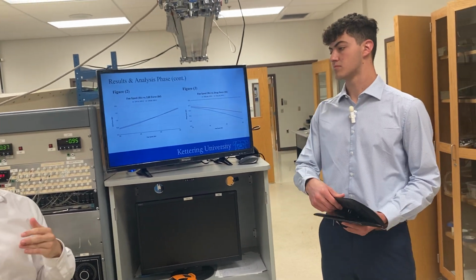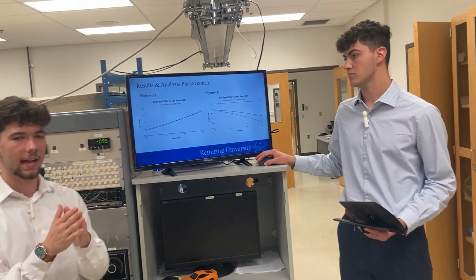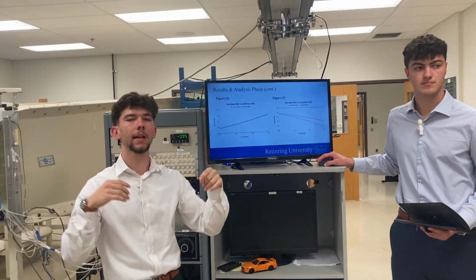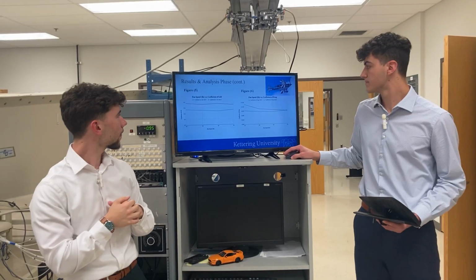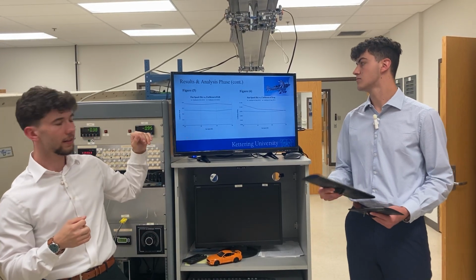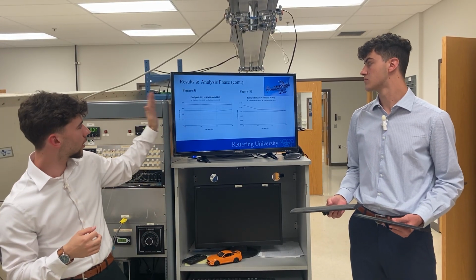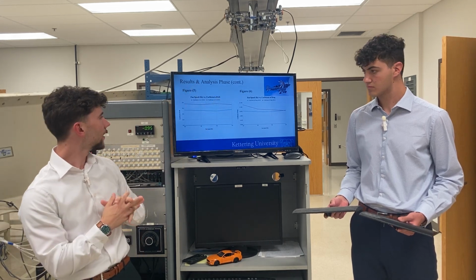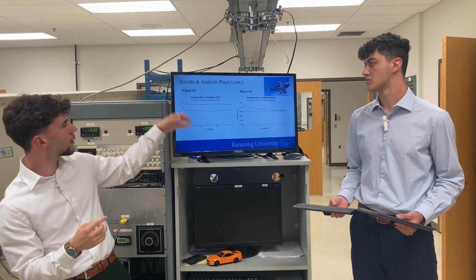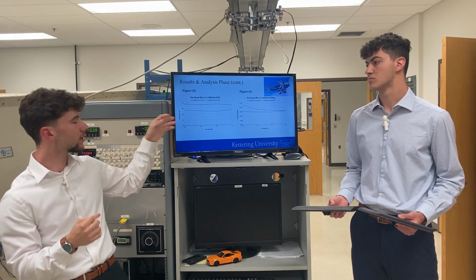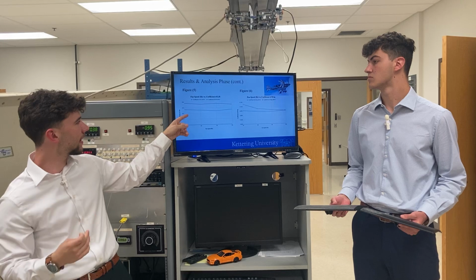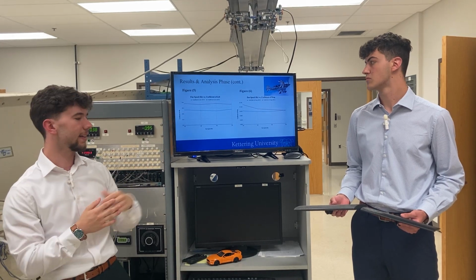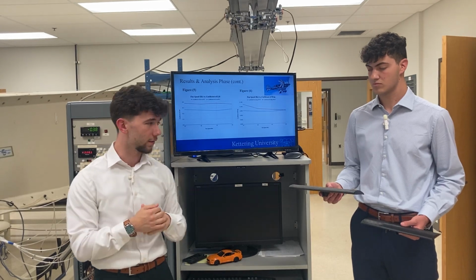This is what we would expect from a foil with a high aspect ratio, as you get longer and skinnier, the wingtips are going to be farther from the base of the wing, meaning they are going to produce less drag force. Figures 5 and 6 here are the fan speed for each foil versus the coefficient of lift, and the fan speed for each foil versus the coefficient of drag. Now here, again, this is similar to figure 2 that we showed previously, which displayed that the lift forces were inconsistent, and again, that can be attributed to the rough surface finish.